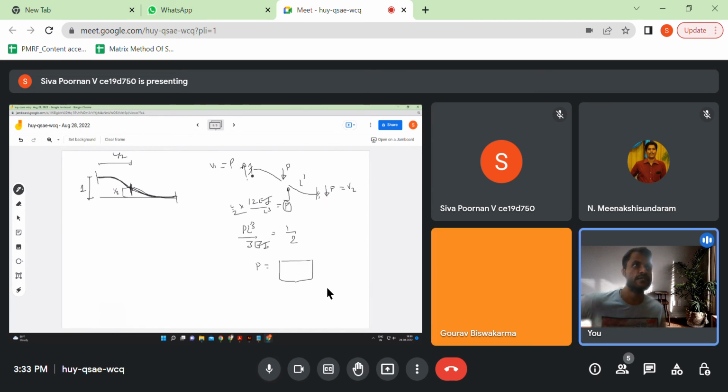And that will be same as M1 here for this cantilever. You can find out the signs by just imagining whether it will be anti-clockwise or clockwise. Anti-clockwise means positive and clockwise you take as negative. The sign convention you adopt need not be the same as what I am saying, but be consistent in what you use. So this way you can easily solve this problem.